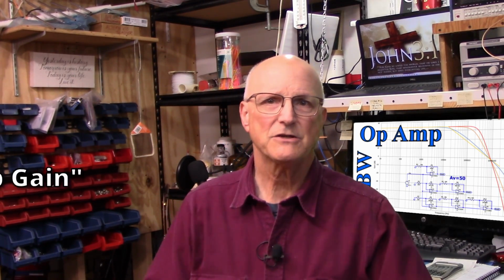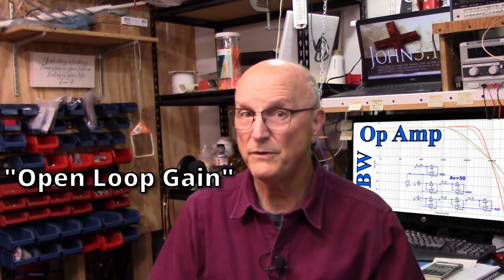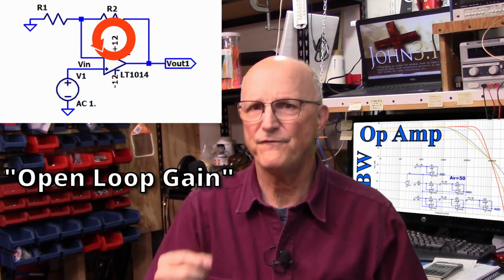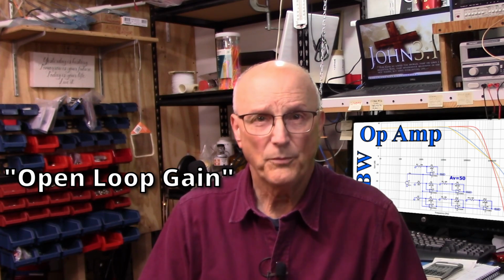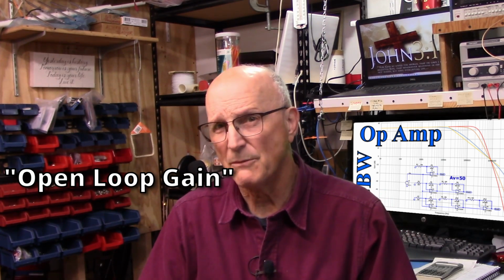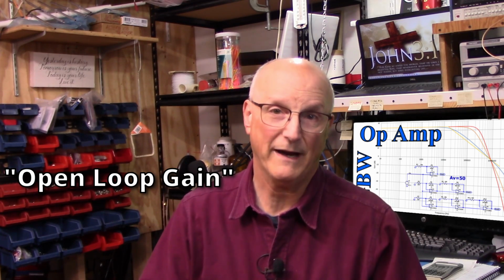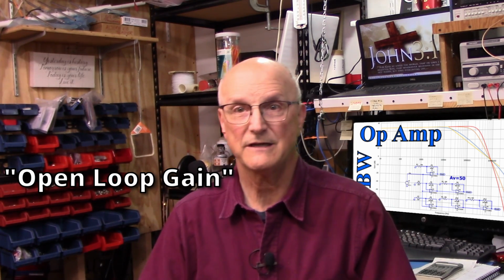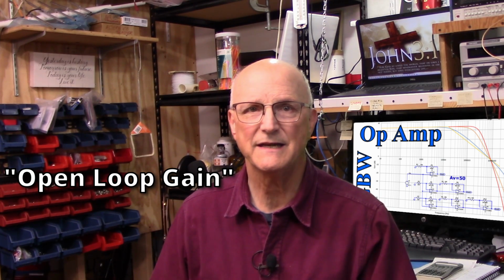This limit is called the open loop gain. When we talk of a loop, we're talking about the feedback path. It forms a loop. Open loop gain is the absolute maximum gain available with the op-amp, assuming that there is no feedback resistor of any kind. It is an open loop. This measurement is made at DC.